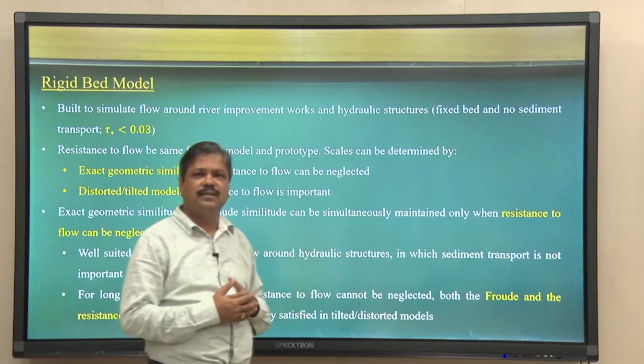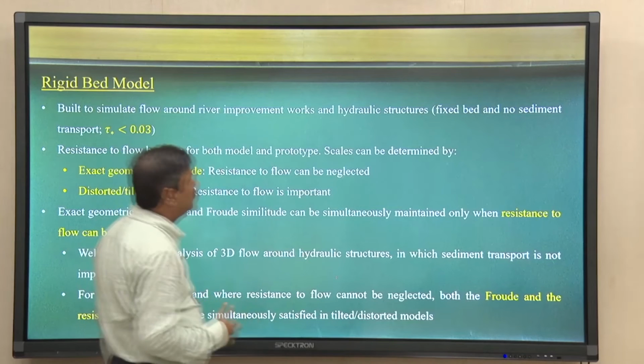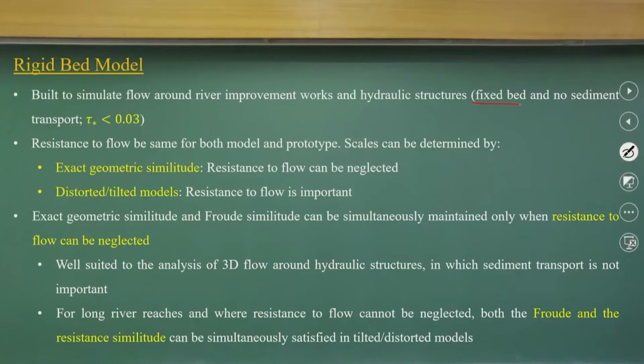So, we can go for rigid bed models, which are fixed bed, as the name implies, with no sediment transport. That is what we consider when the silt parameter is less than 0.03.